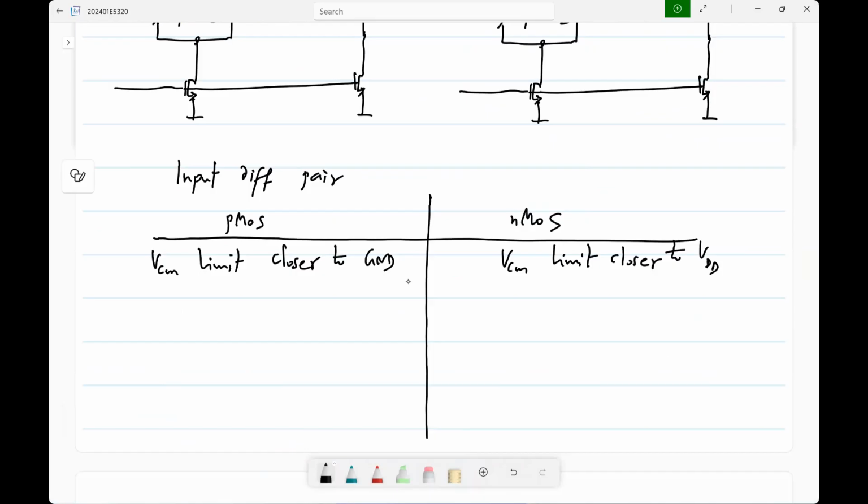The main difficulty in any processing is that you have a surface, an interface between two materials. It is very, very difficult to keep that clean. Whereas inside the bulk of the material, things can be perfect, or at least close to perfect. So any phenomenon that occurs at the surface is prone to garbage like flicker noise.